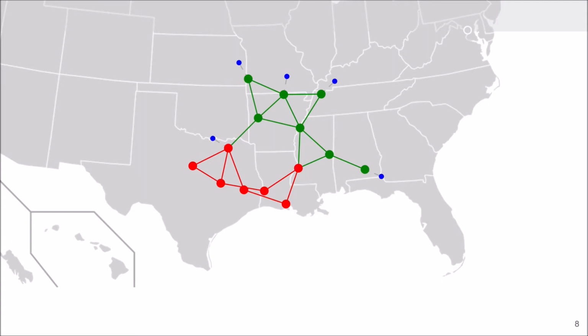What I want to clarify here is that this is separate and distinct from a black start scenario. In black start, while there may be some damaged devices, the assumption is that load can still be delivered in the system, but that devices need to be brought online in a specific order. In this case, we're not saying that the grid frequency is down, just that there's a significant section of the grid that has been damaged and load cannot be delivered. So this is a much longer term question of how do you prioritize and begin to order these repairs that need to be done.